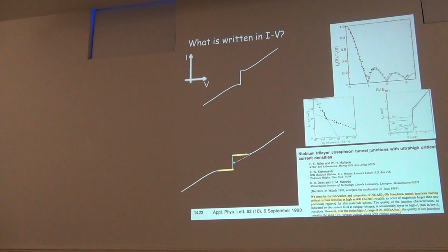You see that when the barrier is thick, everything is reasonable. When the exposure is very short and the barrier much thinner, you lose control and you lose correspondence between RSJ behavior and these curves. You cannot associate any capacitance, anything. You have some kind of problem from an electrodynamical point of view. I would be very careful putting these junctions in any circuit, because I don't know their electrodynamics. I may have artifacts when working with microwaves.